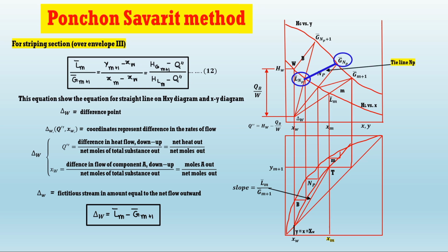And as we know, the vapor leaving the reboiler is in equilibrium with the residue, hence the reboiler also shows an equilibrium stage, which is shown by tie line B in the diagram. As we already know, if we don't have XY data to draw the equilibrium curve in the composition diagram, we can project tie lines and we can draw the equilibrium curve.